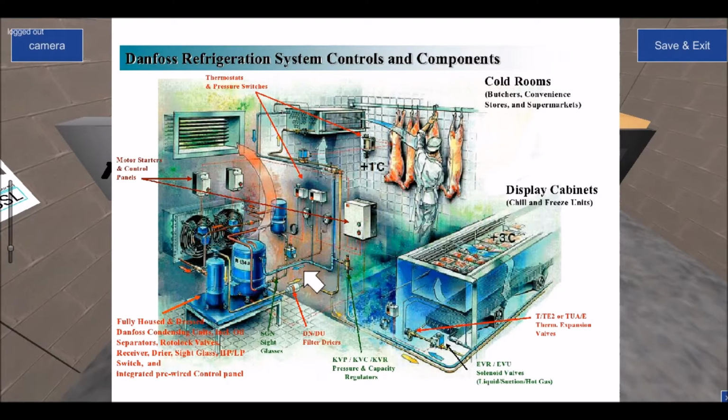So basically there's a pressure switch, and what I'm trying to study here is which one is connected. There's a low side pressure switch and a high side pressure switch, and I'm trying to figure out which one is connected to the low side, the one that has the pipe to the suction side of the system. It's quite hard to see here. There's the suction pipe, there's the pipe work. So this is representing your low side pressure switch.